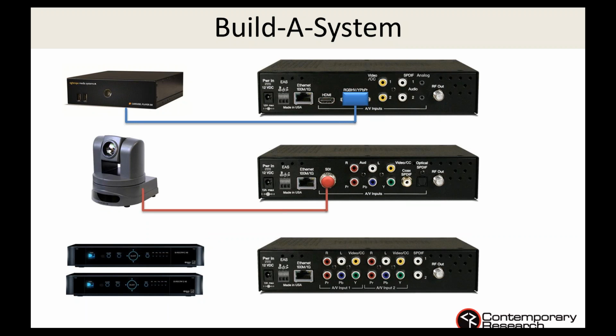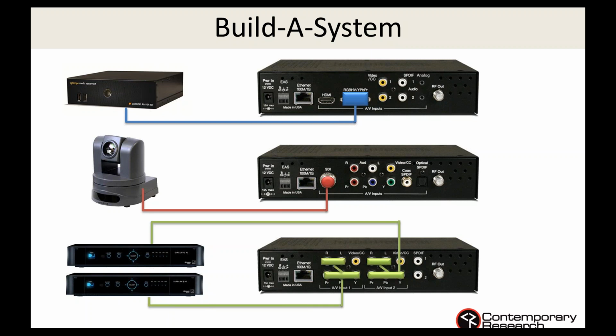Often for sports bars, they're using DirecTV, and the boxes used for sports bars still have component outputs. So typically they'll take two DirecTV receivers, connect them to the two component receivers, and broadcast that as a channel, and then 2.1 and 2.2 are the two cable boxes. Then you add those up, typically about 8 to 12 channels in a sports bar.